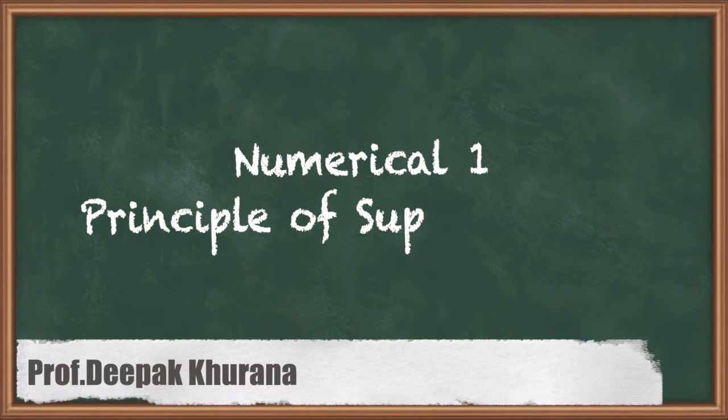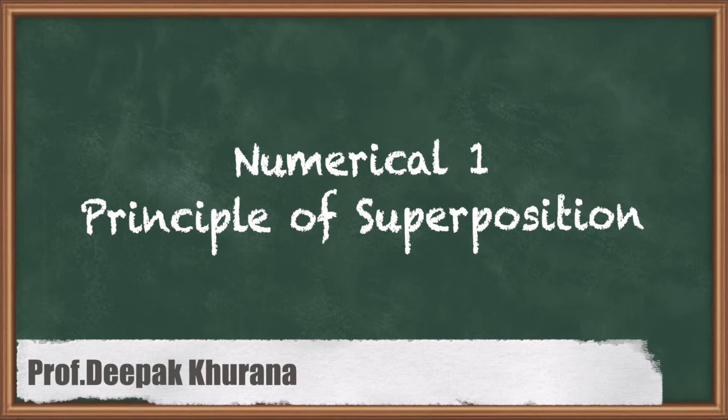A steel bar of 25 mm diameter is acted upon by forces as shown in the figure. What is the total elongation of the bar if the modulus of elasticity of the bar is 190 gigapascal? So this is a question of the principle of superposition, in which there are various forces acting on this bar.